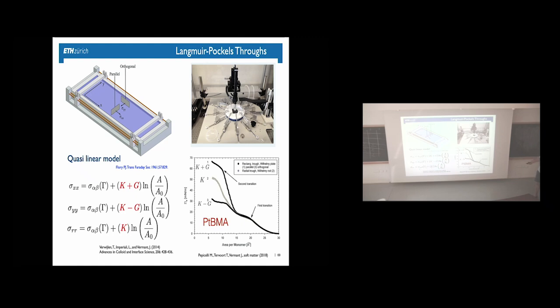Here you see a polymer, poly-tert-butyl methacrylate. It's a methacrylate. It's a glassy polymer. You can spread it fairly nicely. I have a surface pressure area isotherm. At high areas, I have a gas. The molecules are individually happy. They're little blobs floating around. And then they bump into each other and form a liquid. And then I have a liquid-solid solution. And I see I have a solid because now I start having a shear modulus. And the shear modulus influences the measurement. So clearly, in this case, the measurement of the plate hanging like this, or a radial geometry, give different results. So it cannot be a state property.